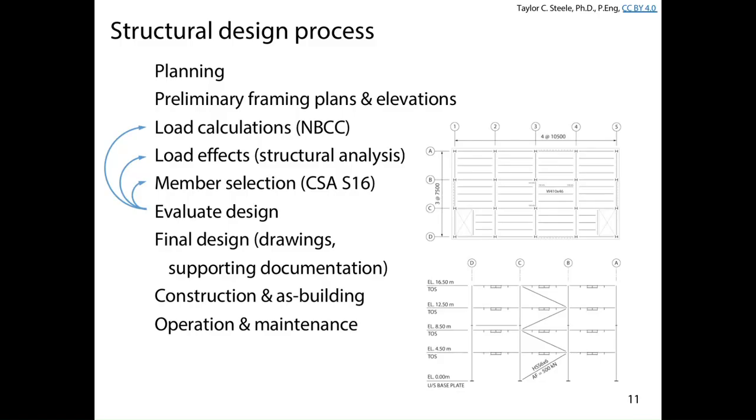Throughout the time, I asked you to evaluate the design, and there's a couple things to that. There's calculating the strengths to verify it works, and there's also comparison to design alternatives. In your groups, you had 4 different framing plans. You could consider those design alternatives. And throughout the course, I've been asking you to compare the weights of the braces, how efficient is everything, the total weight of columns, beams, and girders. How does everything compare across the 4 framing plans?